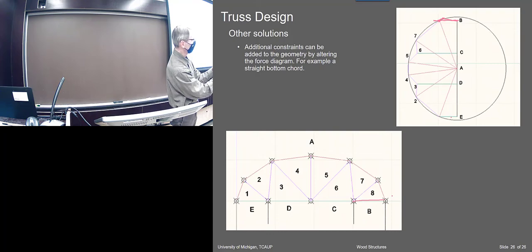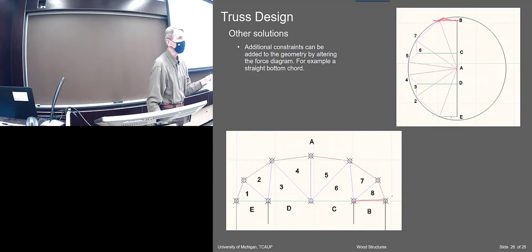This is 4x6, and then I've got to pick the right length, and then I can read across and see what the load capacity is, right? So if you've got the load, you can read this table and find your member. So you should be able to use this to quickly pick a size for the member, right?